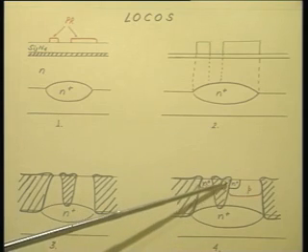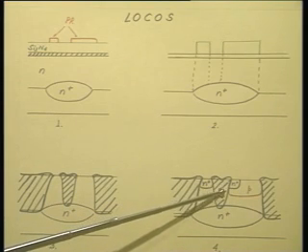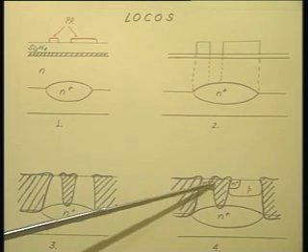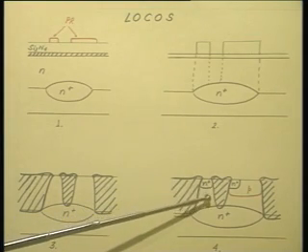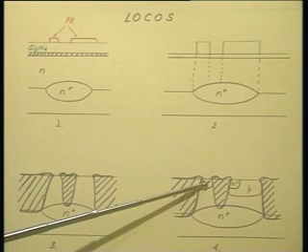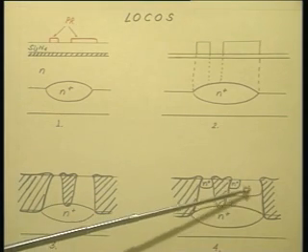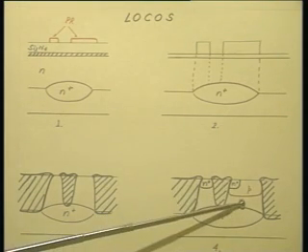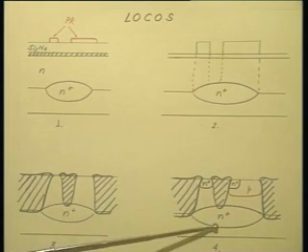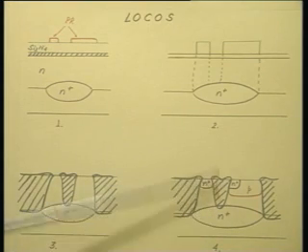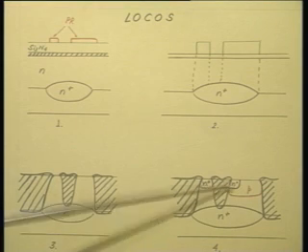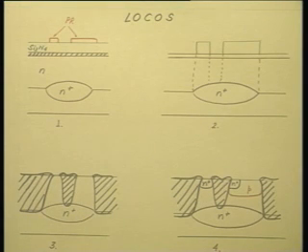You see emitter is also stacked against the oxide here, and you use this region in order to realize the collector contact. This N plus region is going to be used as the collector contact, this N plus as the emitter, P is the base, and then underneath you have the collector and the buried layer. So, this is your collector path. Path of the current flow is like this. You are forcing the current to go through the buried layer, so that the collector resistance is cut down. Okay.